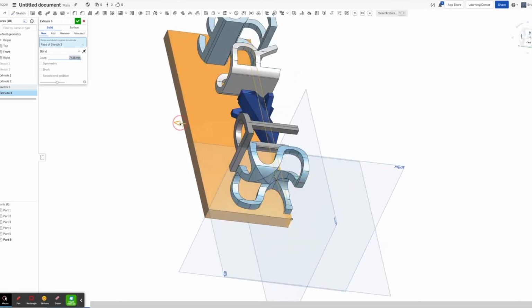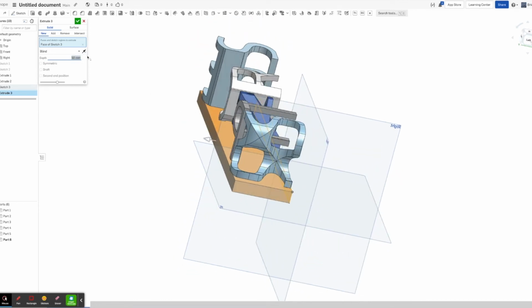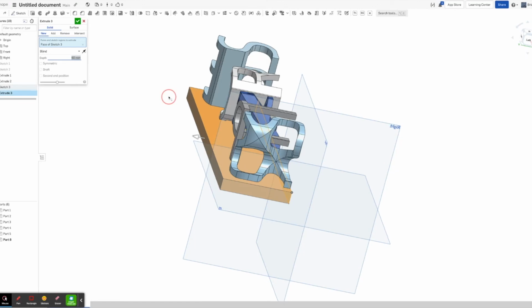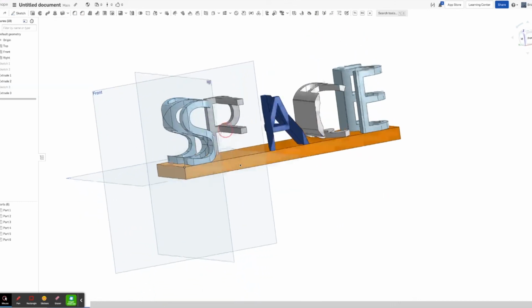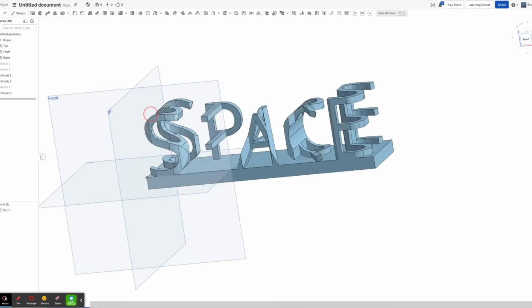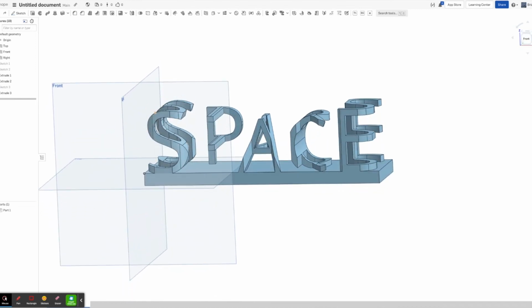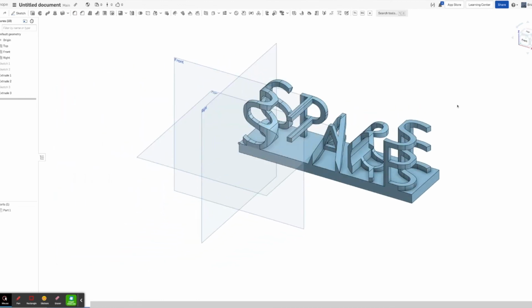A little bit too far, like so, maybe 50 millimeters, or maybe, let's try 60. I think we can do 55. And confirming that. Actually, I'll merge with all. And by making this intersect extrusion, I created this pretty interesting design right here.